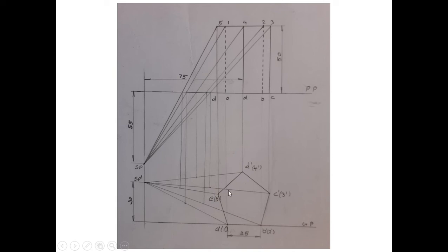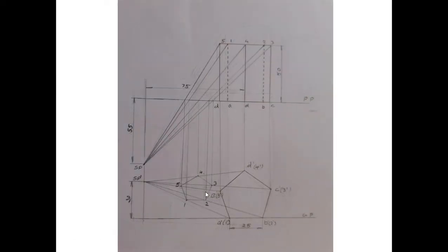So that means that face will be the same pentagon. We won't get another separate pentagon. Whereas the other face, 1, 2, 3, 4, 5, is behind the picture plane, some 50 mm behind. So you need to draw the rays of vision corresponding to those points only. So you'll get 5 rays here, and you'll get 5 piercing points here. These are rays of vision corresponding to those points, and those points you drop to the corresponding line. You'll get some points. Then you name it as 1, 2, 3, 4, 5, and you connect them by using lines.